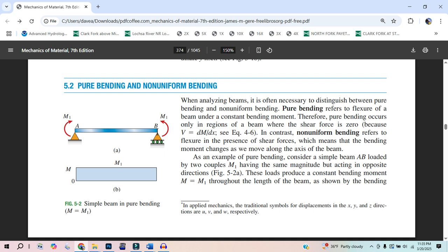Theoretically, it would be impossible because a moment is two opposing forces separated by some distance. So it's very useful. And this is where I messed up the other day. I said, oh yeah, this moment would be an outward force this way and then an inward force that way. It's like, no. If we say that this is the moment, then I could apply a force at the top of this beam right there in this direction, and then go to the bottom of this corner and apply a force this direction.